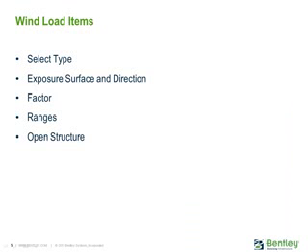After the wind load cases are created, you can now add wind load items to those load cases. The wind load items will use your wind load definitions, and by entering the different parameters, such as the type or the exposure, the factor, to those wind definitions, you can instruct STAAD.Pro on how to apply the wind load to the model. In addition, we also do have a toggle to define this as an open structure.